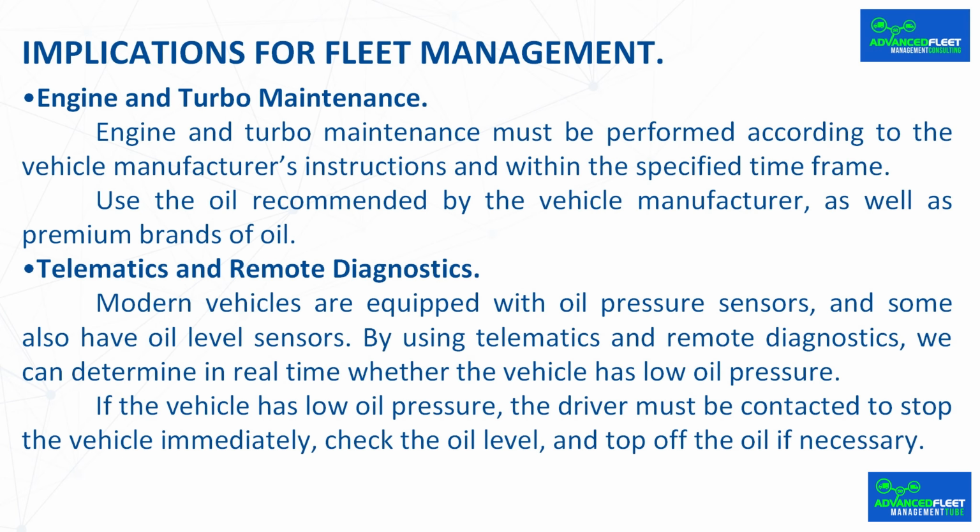Engine and turbo maintenance. Engine and turbo maintenance must be performed according to the vehicle manufacturer's instructions and within the specified time frame. Use the oil recommended by the vehicle manufacturer as well as premium brands of oil. Telematics and remote diagnostics. Modern vehicles are equipped with oil pressure sensors, and some also have oil level sensors. By using telematics and remote diagnostics, we can determine in real time whether the vehicle has low oil pressure. If the vehicle has low oil pressure, the driver must be contacted to stop the vehicle immediately, check the oil level, and top off the oil if necessary.